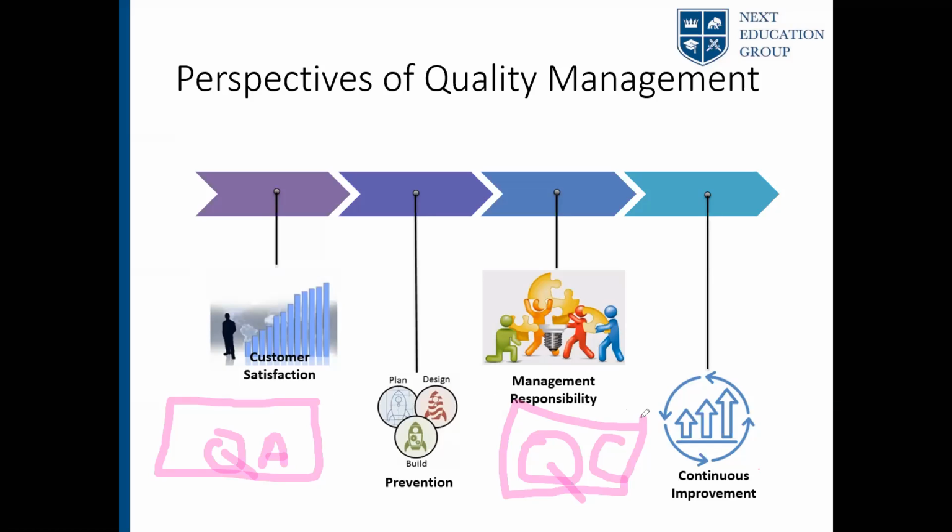So quality assurance is ensuring that your final product would meet the quality standards. That includes planning properly, training your employees on the jobs they are doing, designing it properly, and proper maintenance of your machines. But when it comes to control, it's to ensure that non-conformance products or bad quality products are not released to the market. So you observe, you inspect, and if there's something of bad quality, you would stop sending it to the market. So as Dimitri said, quality assurance is more proactive, a preventive measure. Quality control is a more reactive approach.